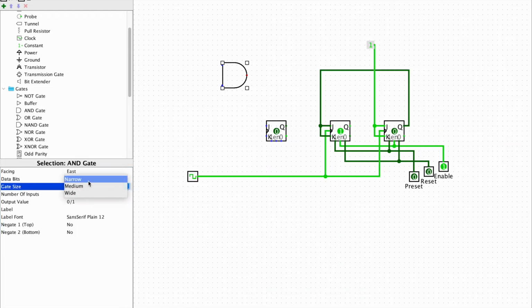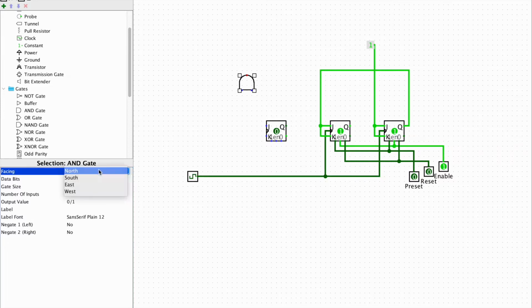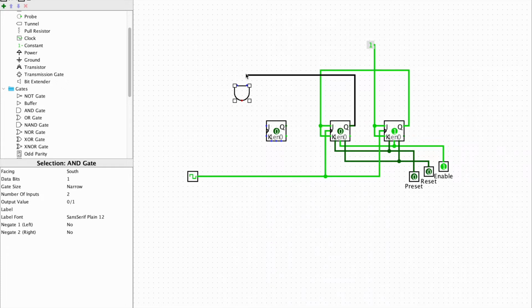Let me make this a little small so that it seems neat with the circuit. So I brought in the AND gate, and I will connect both these Qs. Here is the second Q, and here we are bringing up the first Q. So we want the JK flip flop to toggle whenever both the least significant bit flip flop and the middle flip flop turn 1.